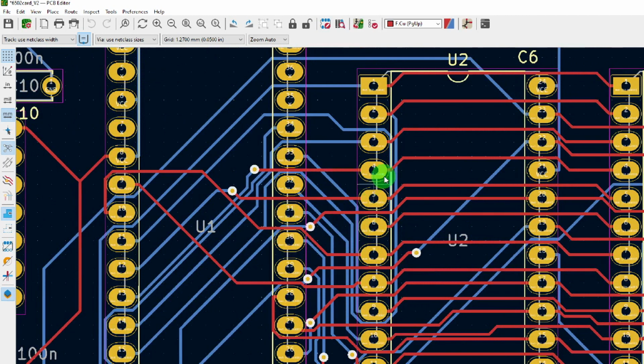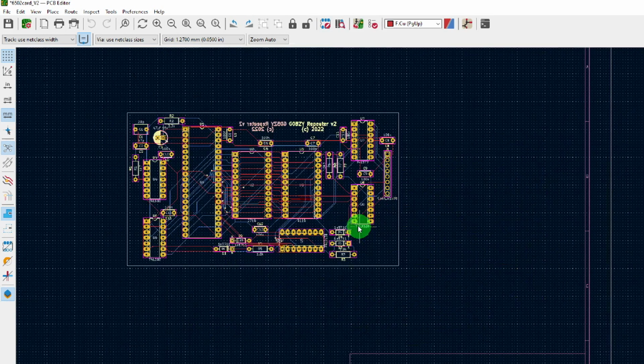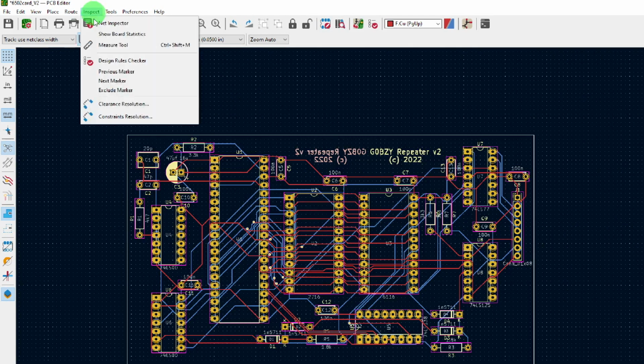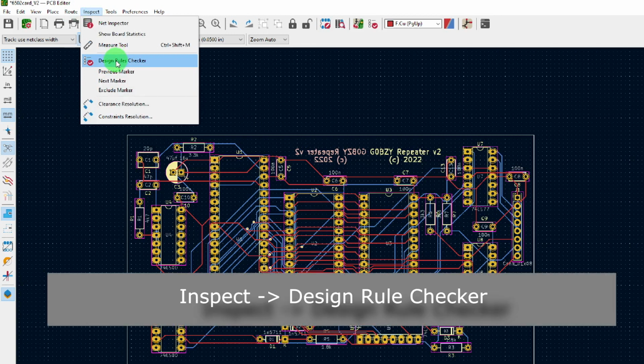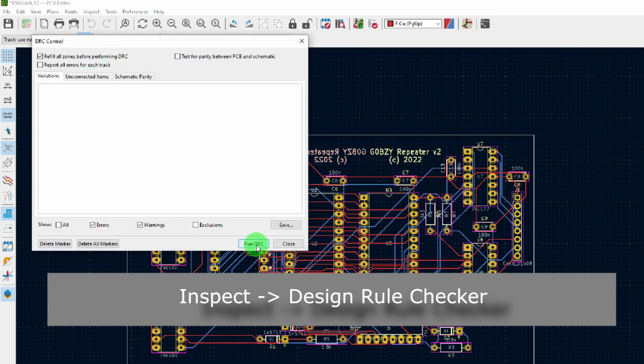You can see here we've got copper track going through between pins, and then we hit a via here, then it continues on the other side of the board, and it goes down to this pin 13 on that chip there, and so on. So yeah, it all looks pretty good. Now what we can do here is a design rule check, and let's just see if we've got any problems here. So let's run that, run design rule checker.